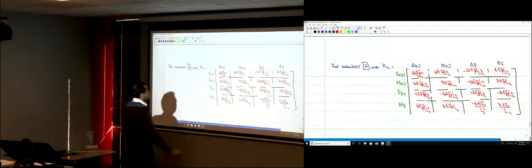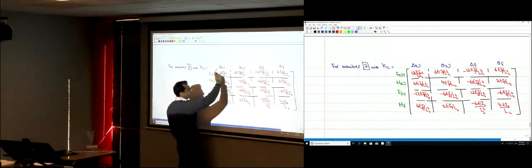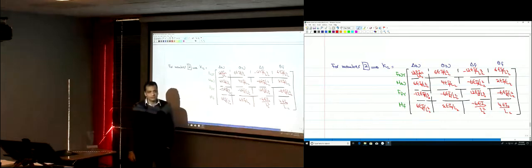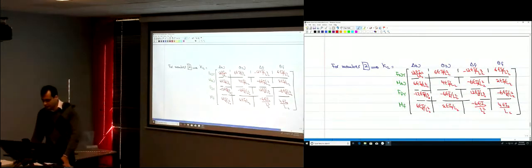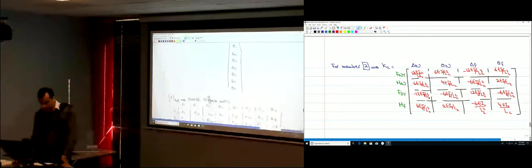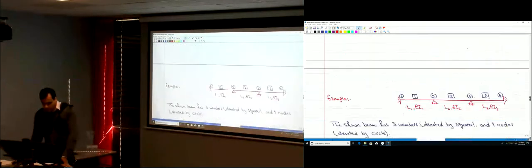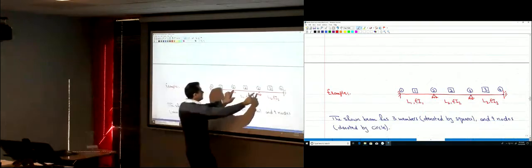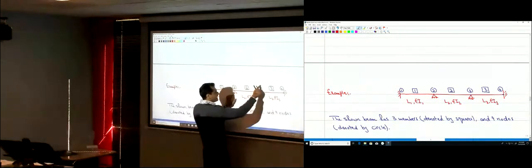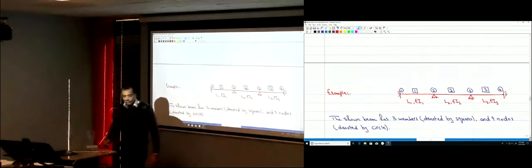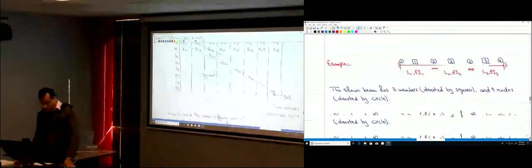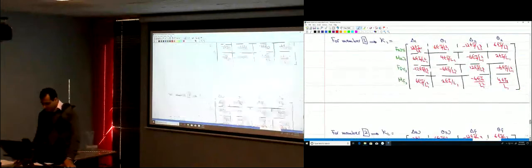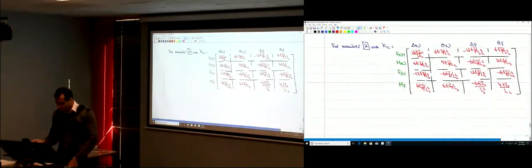And now, K2 is relating forces to displacements. What forces and what displacements? 2 and 3. The start here, the near end of member 2. This is member 2. The near end or the start is node 2, and the end is node 3. So it's actually relating the forces and the displacements at node 2 and 3 together.